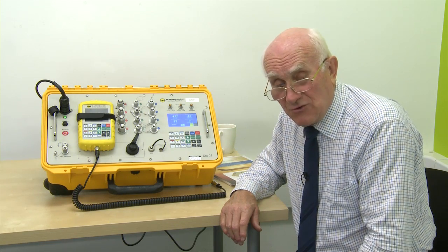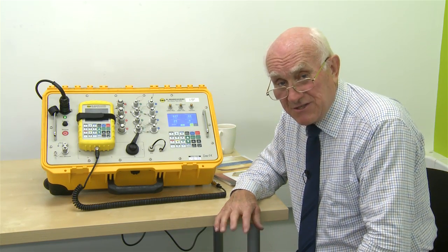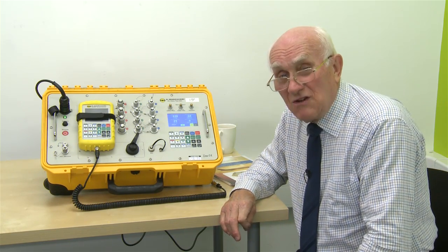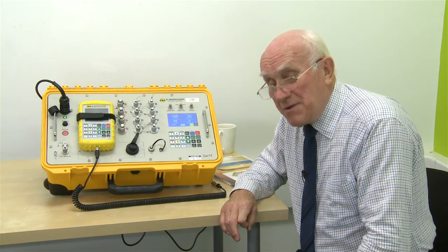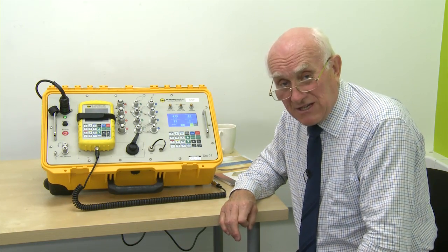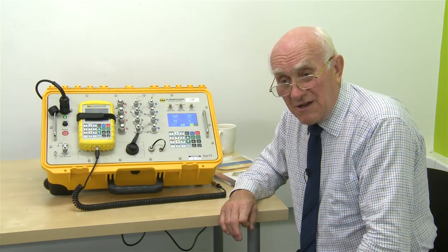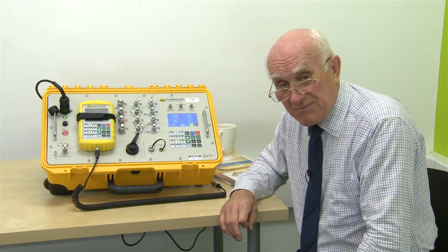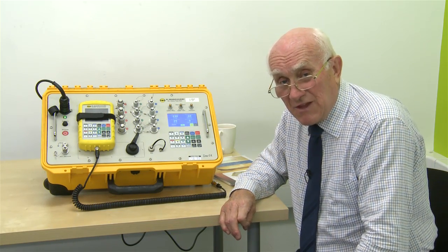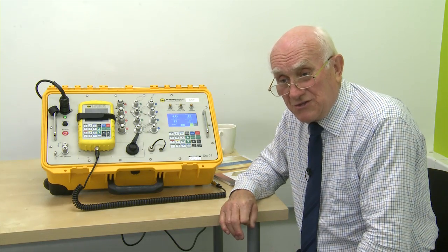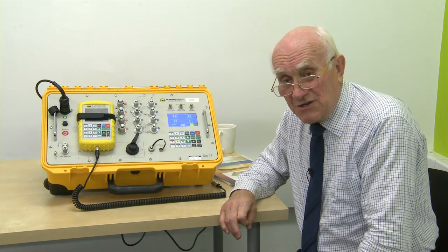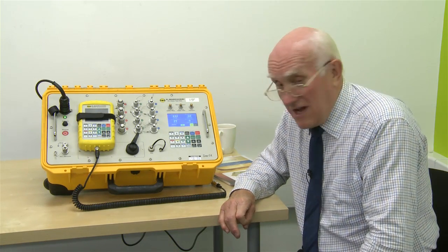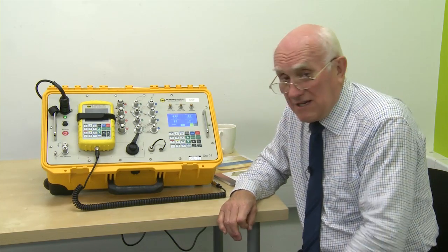which is the MPS 45, is a twin channel instrument, a conventional pitot-static altitude and pitot-total for airspeed. The MPS 49, however, is a three-channel instrument. Not only does it do the conventional static and pitot, altitude and airspeed, but additionally a third channel for angle of attack, so that you can check out the more recent pneumatic angle of attack sensors on the aircraft. Here today we happen to have a three-channel instrument.